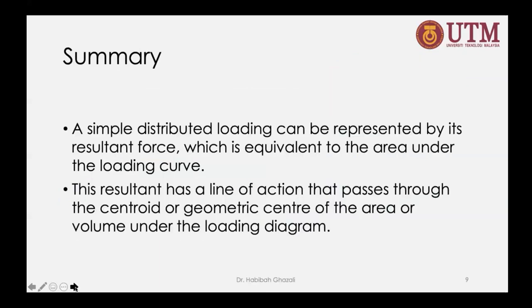Okay, so that's a very simple revision on distributed load. In summary, a simple distributed loading can be represented by its resultant force, which is equivalent to the area under the loading curve. This resultant has a line of action that passes through the centroid, or the geometric center, of the area or volume under the loading diagram.